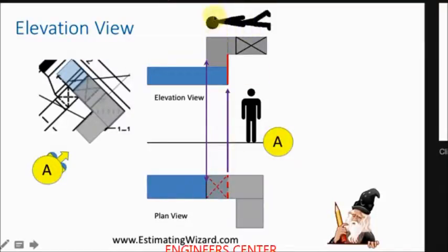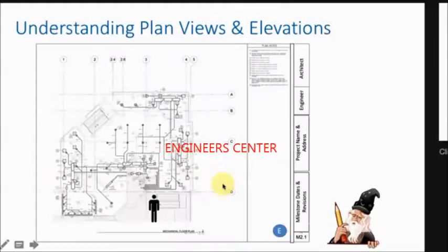So if you're up there flying around, you can fly above like the wizard. You can see down. You would see a solid line there, just like you do there, just like you do here. But here you couldn't see this line in the back because you got this duct blocking your view. So to represent that hidden line, we make them dashed. So he's looking down, but he can't see through the metal, but this represents a supply. And so that's how you tell hidden lines.